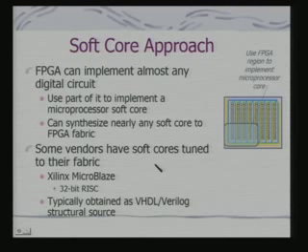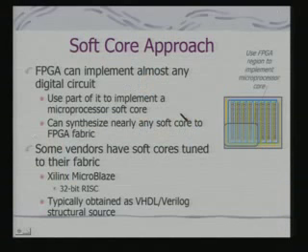So, let us first look at the soft core approach. In fact, if you remember, we discussed that in the last class also, that if I am doing a platform based design with a soft core availability, I have certain freedoms in terms of choosing the processor architecture, choosing the IO devices, choosing even the register set which a processor can have.